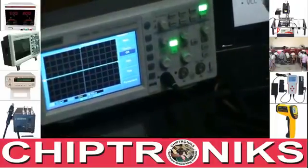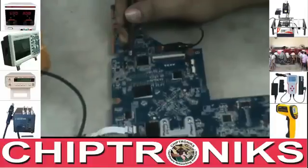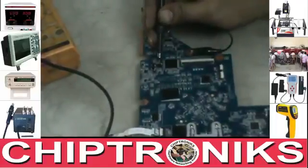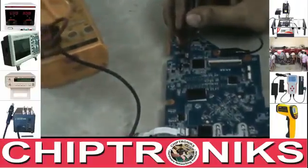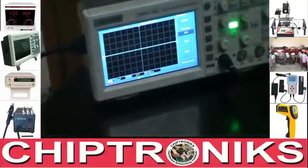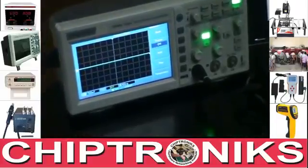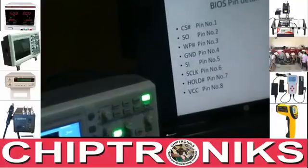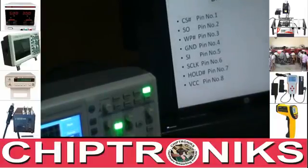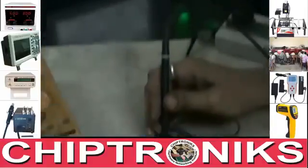Now I'll check the signal output on pin number 2. No signal, nothing. It means here we do not get any kind of signal on pin number 2. This pin is the output pin. Here we check whether our BIOS IC is working or not, whether the file inside is working or not. Now on pin number 2, I am not getting any kind of volts or signals.